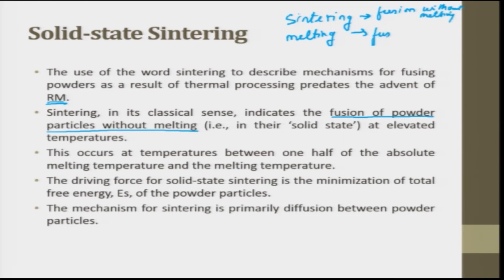So, here it is fusion with melting. Okay, that is in their solid state at elevated temperatures. This occurs at temperatures between 1/2 of the absolute melting temperature and the melting temperature. So, the driving force which drives solid state sintering is the minimization of the total free energy of the powder particles.